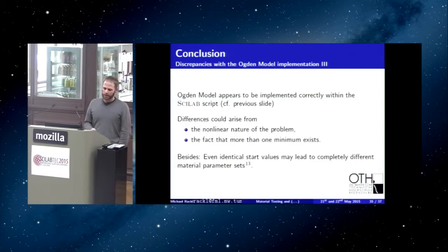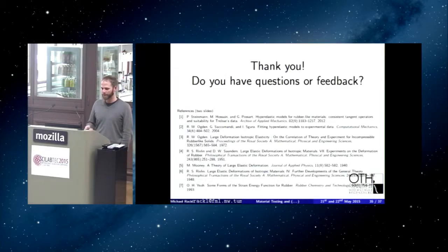So generally, it was really important for us to have the script. But summing it up, if you ever have to fit hyperelastic materials, I strongly suggest you try out lower order models first, because even if you might have a really nice fit in a stretch and stress curve, it might end up crashing your simulation over and over again, because higher order models just tend to be unstable, and there might not be the need to do higher order model fitting.